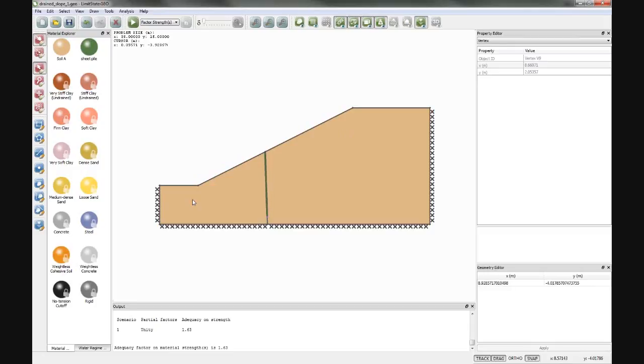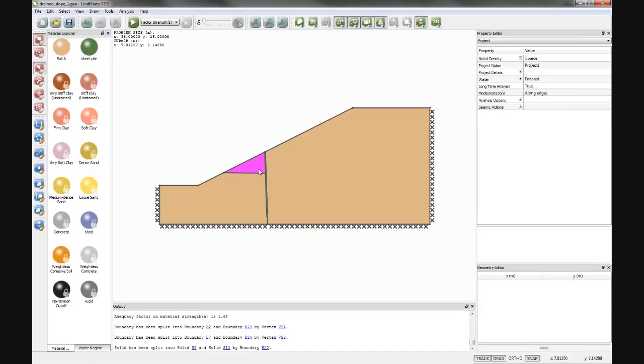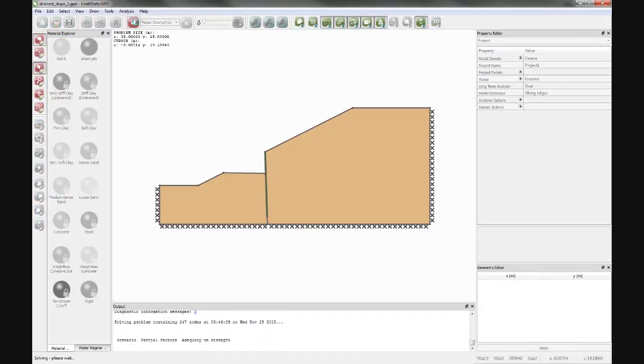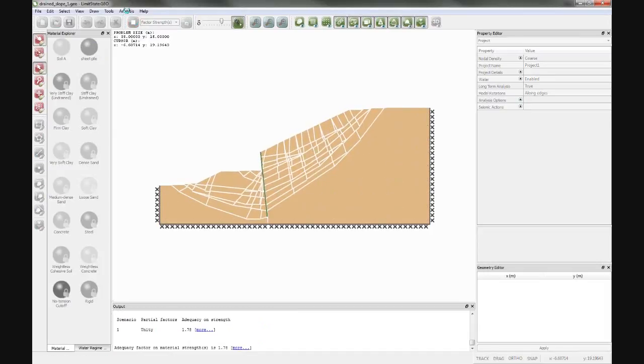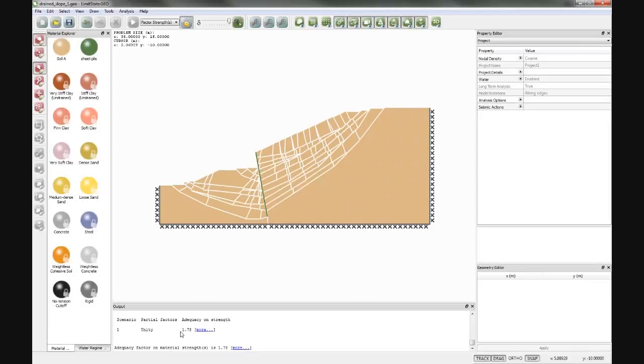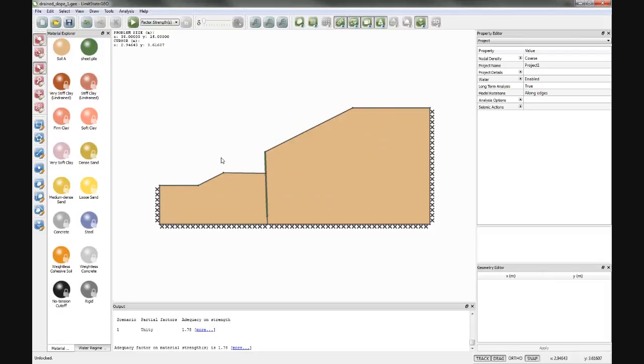And if you have the long wall, then if you want, that might facilitate, if I draw a line there, excavation of material if you need somewhere to do some construction, and you can look at how that stability plays out in that particular case. So here that wall has given us a stability of 1.78, so that's still higher than the original 1.63. So hopefully you can see it's quite easy to play around with the geometry and explore possibilities.